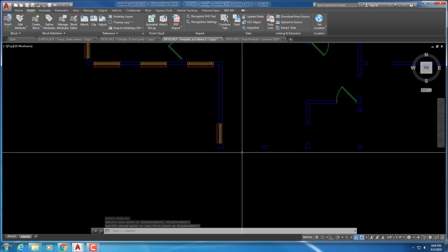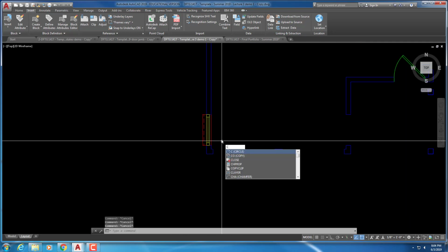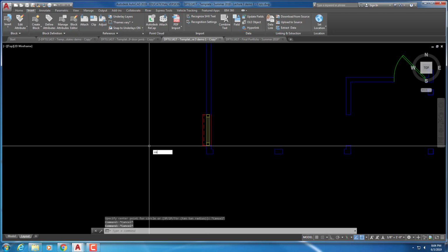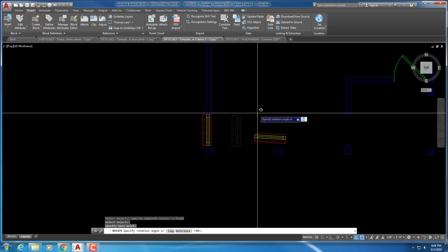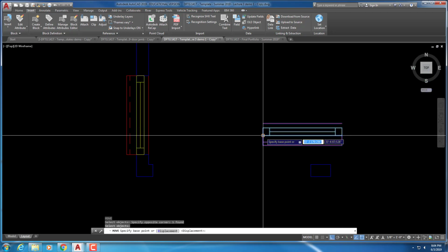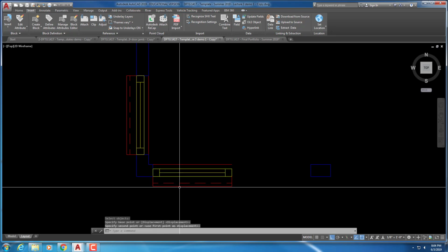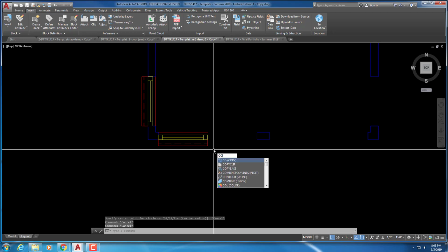Alright, in the front it's got a W24 window, which is 2 3.0 windows, mulled, which means there's no framing between, so it's a 3-foot window and a 3-foot window that butt against each other. Hidden line always goes to the exterior, because it's representing the siding that would be there underneath the seal.